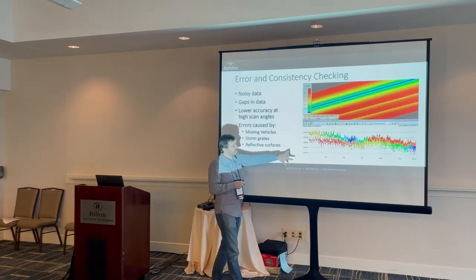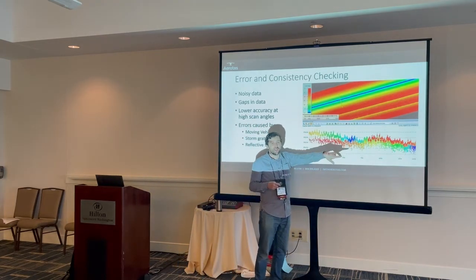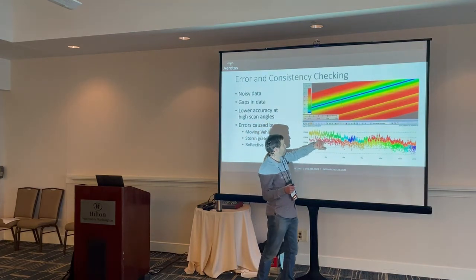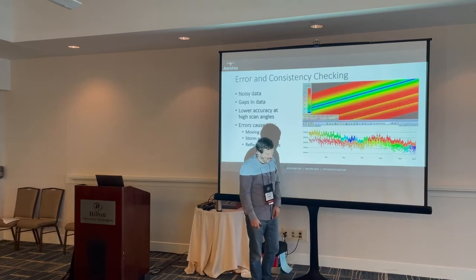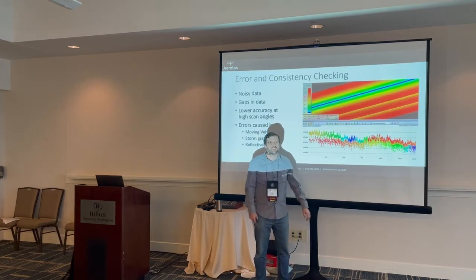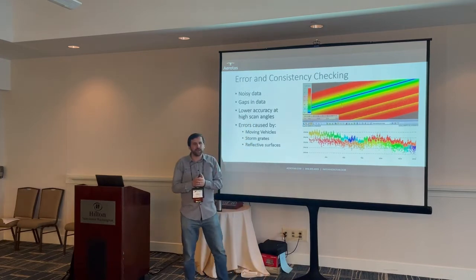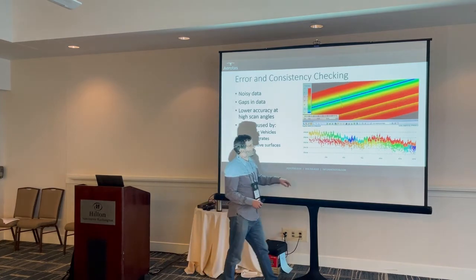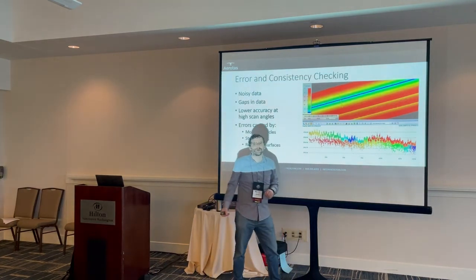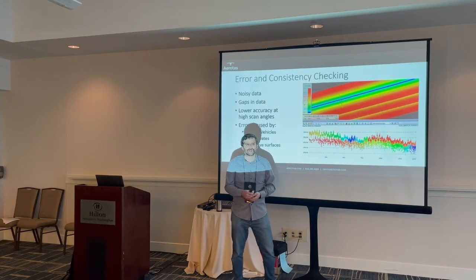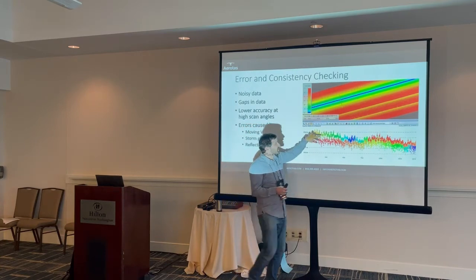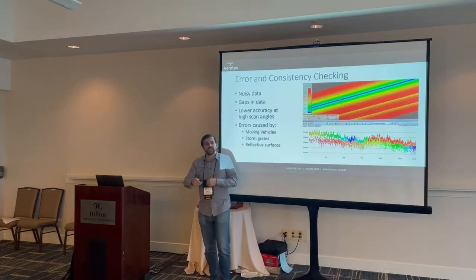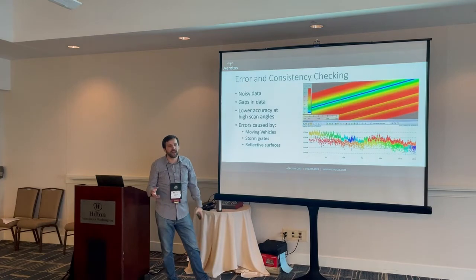When we see things like this, though, this is within the same flight. This might be 2 minutes after when this point was taken from when this point was taken. What this is a sign of is just a little bit of noisy data. It's part of why we like having higher overlap than the minimum required in LiDAR data, so that in something like this, we would typically exclude much of that high scan angle data when we are seeing this type of noise, which winds up getting us a much more consistent point cloud altogether, and gets you better overall accuracy.